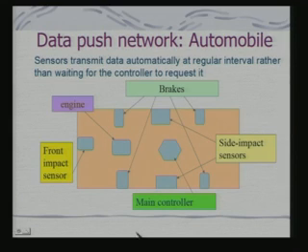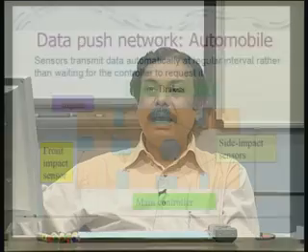Now, what we need to look at is, if such a network has to be built, do we need to have some special requirements? If we are looking at an appliance, say a car, where we would like to have multiple processing elements networked, we do not need all 7 layers of the OSI model to be implemented. So, we shall have a subset of such a model with special emphasis on the requirements of such a system. Such protocols are primarily intended for this kind of embedded applications.